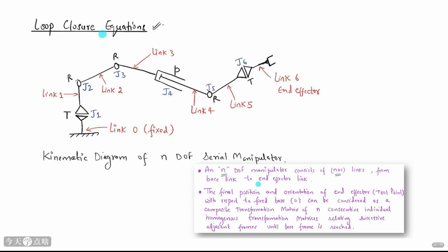The transformation from the base frame to the end effector frame is found by multiplying the individual transformation matrices for each joint. So, we calculate the transformation from frame 0 to frame 1, then from frame 1 to frame 2. The composite transformation matrix, 0T2, is simply the product of these 2 matrices. This matrix 0T2 will give us the position and orientation of the end effector P relative to the base frame. This is the essence of forward kinematics for this simple case.